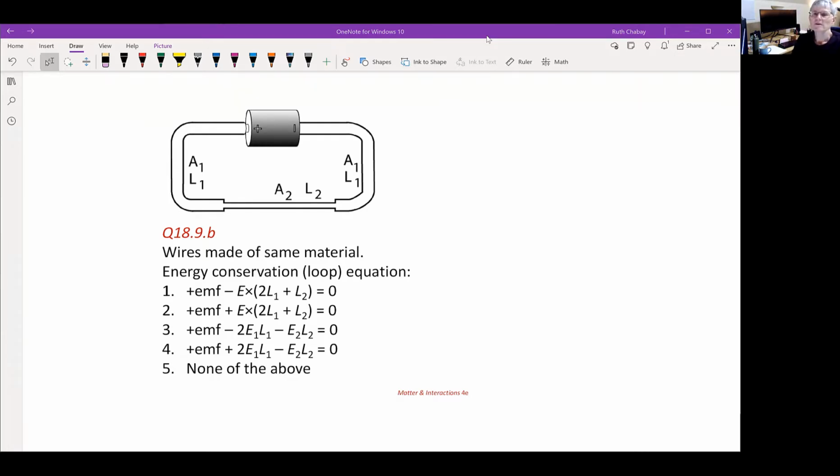Filaments actually burn out due to evaporation. They get hot. They're very, very thin tungsten wires. And they get so hot that some atoms actually start to come off of the filament. And you'll often see kind of a grayish deposit on the bulb in a burnt out incandescent light bulb, and that's because the filament actually evaporated.